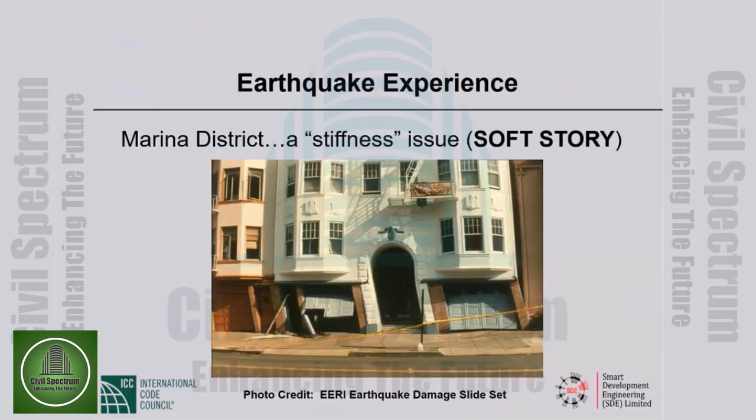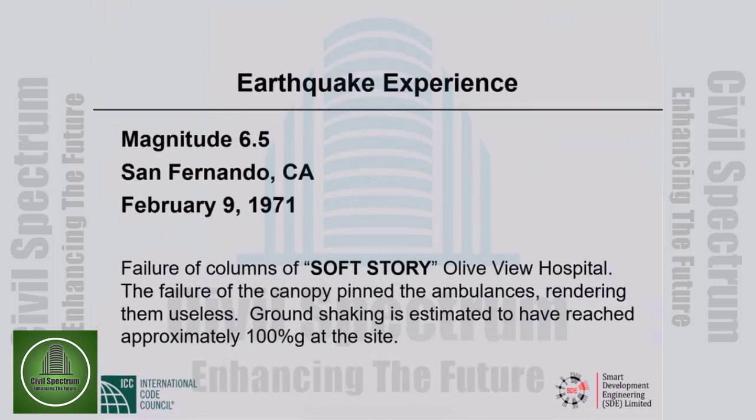Okay? This is a closer up view of one where a garage was created, or this one, all the same. All the buildings had the same thing. This opening was cut in what used to be a shear wall, and now we have only the two pilasters or columns instead of a shear wall, and that is the reason why the buildings have a major problem.